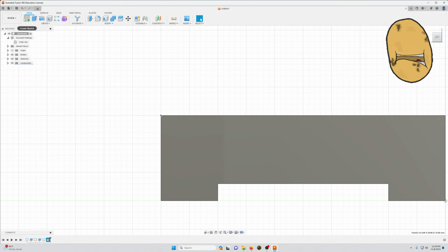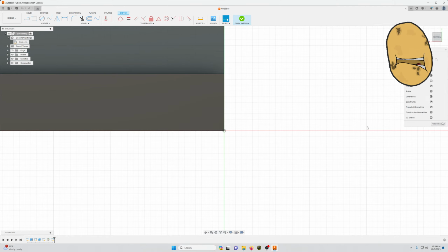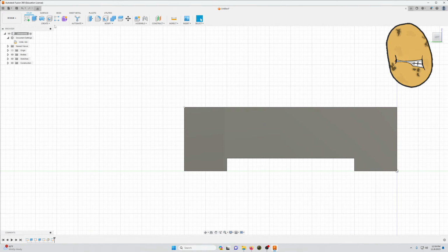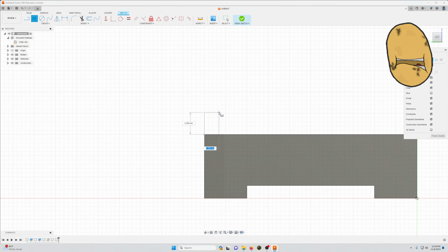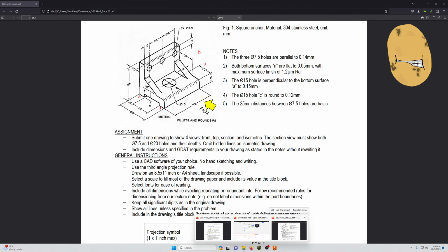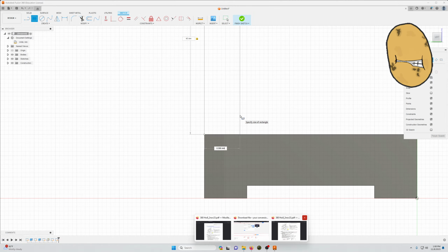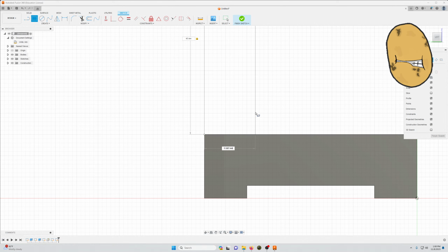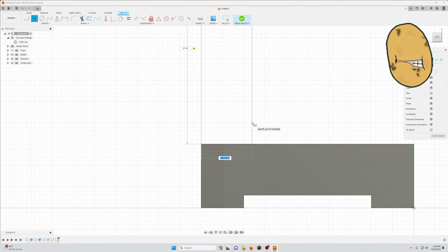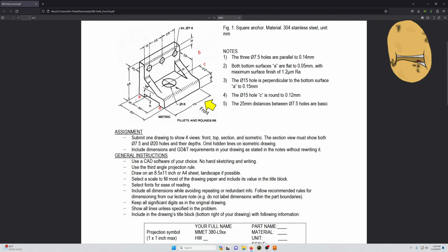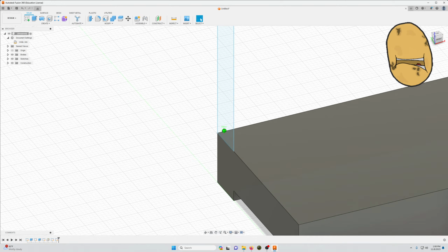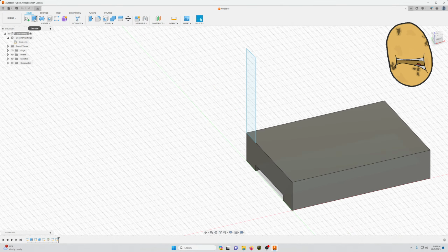And I'm going to go to solid, create a sketch, select my plane, which is definitely not that. This is my plane. And we're going to create another rectangle, and it is going to be a height of 45, like we said. And the thickness, let's see, what was the thickness going to be? 10. So it is going to be 10 millimeters thick. Just go with 10 there. All right, and of course, this is extruded all the way to the end. So we're going to go ahead and extrude this boy all the way to the end as well.